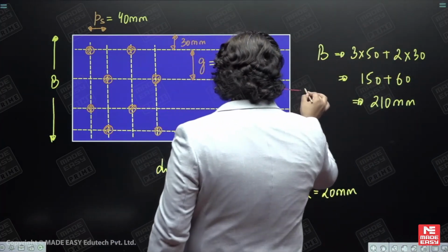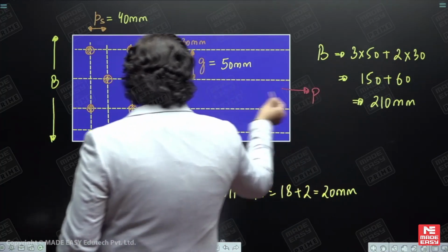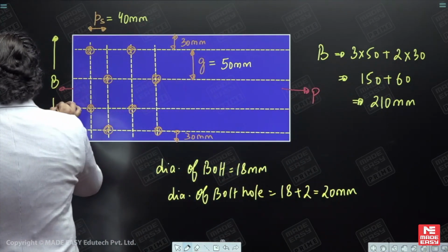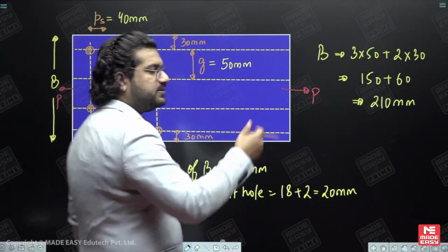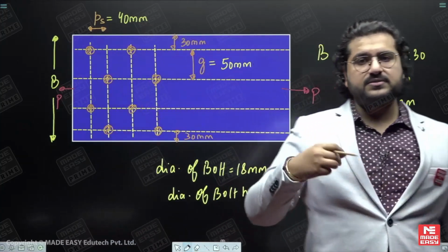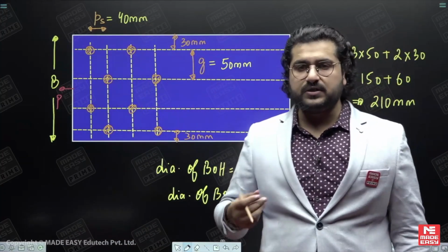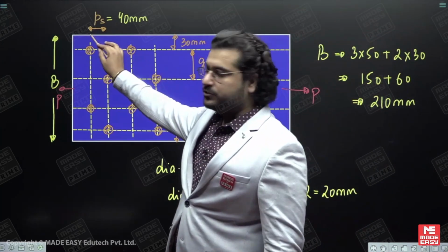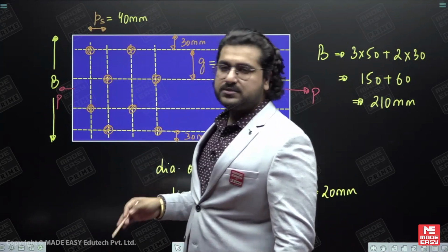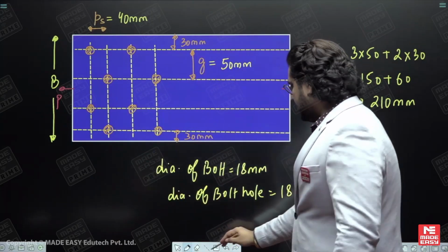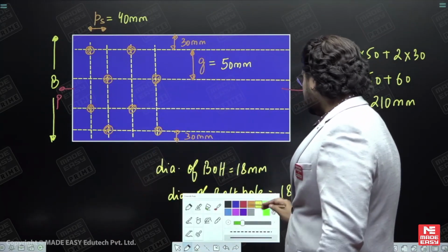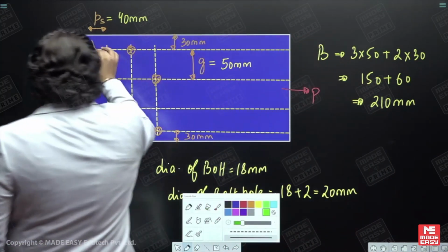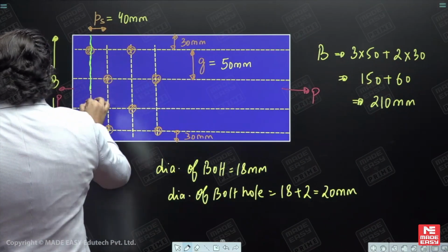So upon application of tensile loading, let us say this pull is P. You can start from any side, either the left side or right side, that doesn't matter. But there are some ways through which you need to see how the failures will come. So failure generally starts from the top portion and then it penetrates downward. This is how the tearing progresses. So let us say the first possible failure path is like this. That means it goes straight away like this.